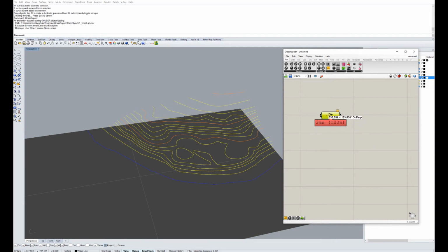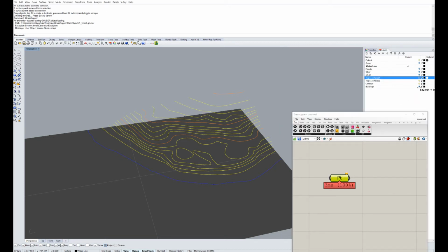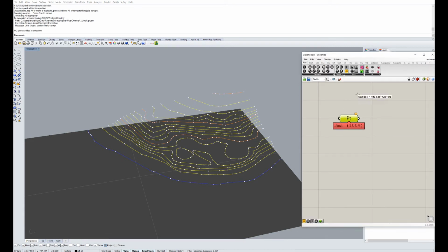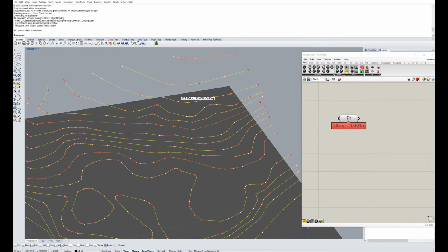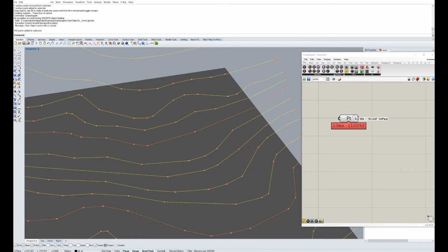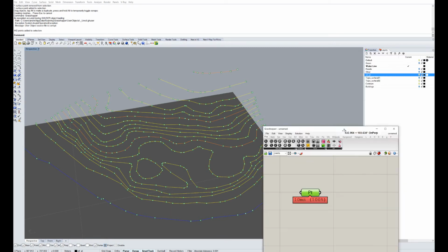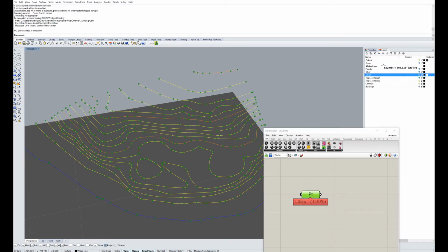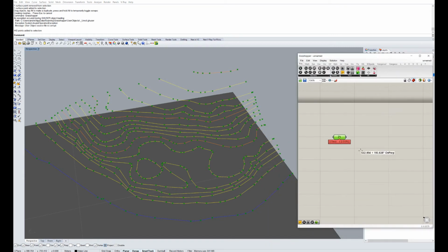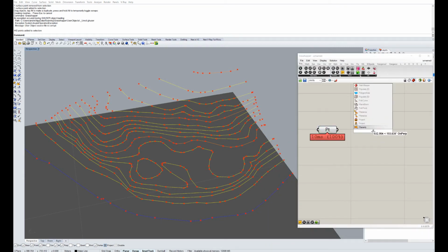What these objects are, basically, is a series of commands that you can link in series. I'm just going to show you a quick example. If we select all the reference points, I'm going to right click on this component and go set multiple points. Now you can see these things have turned red with little crosses on them, and when I click on it, it turns them green. So now these points exist in Grasshopper. I'm going to deselect these, and as you can see, the Grasshopper points don't disappear. Just going to double click again and bring in patch.